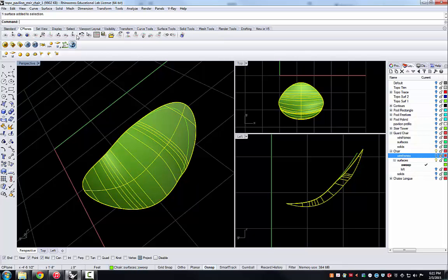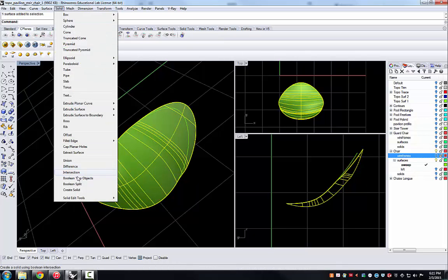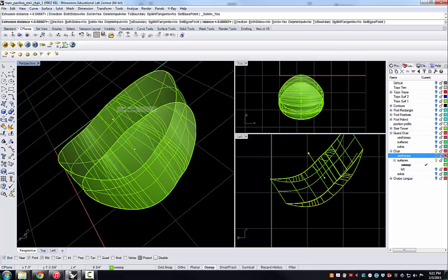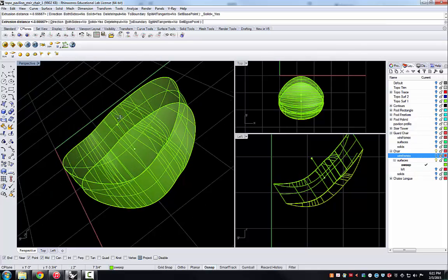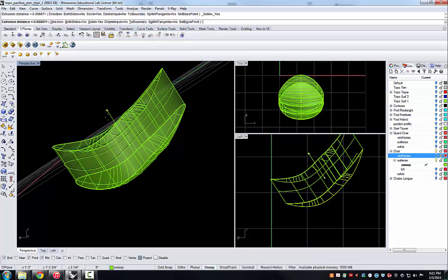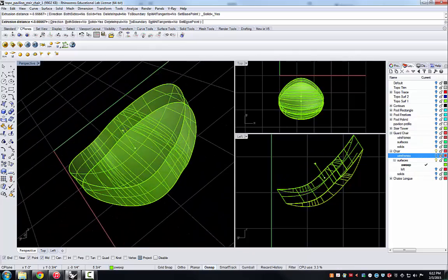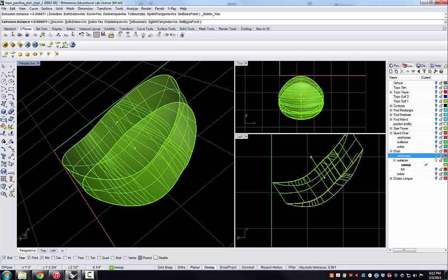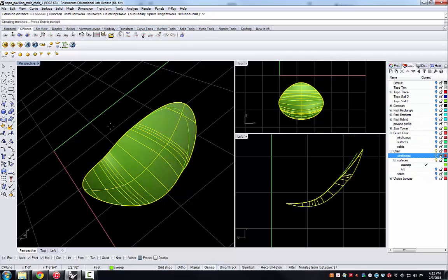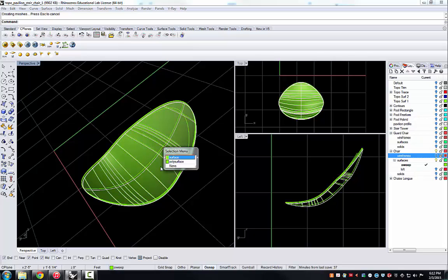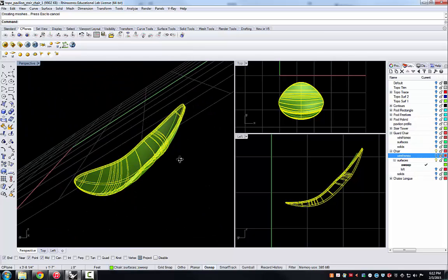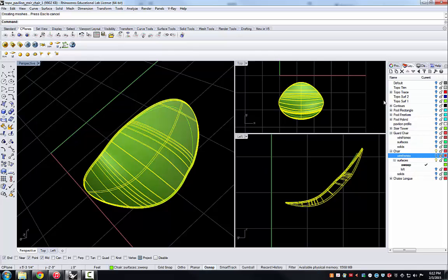And then you can take that and create a solid by extruding the surface straight. And it helps here to be using the newly created construction plane because it will extrude pretty much perpendicularly to the surface. So I could make this 0.5 inches thick and create a new solid called a polysurface that I can move to the solids layer.